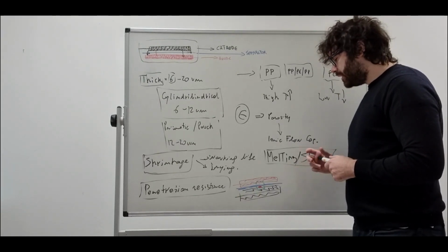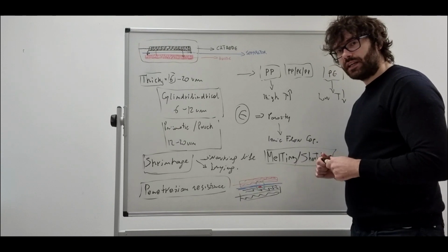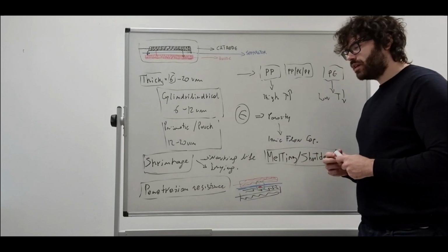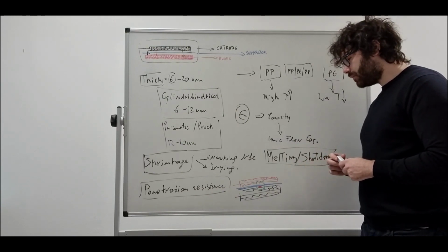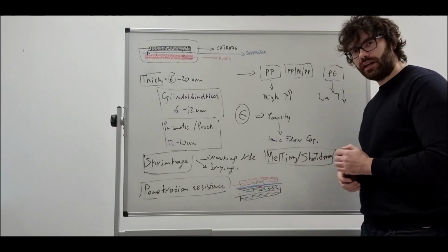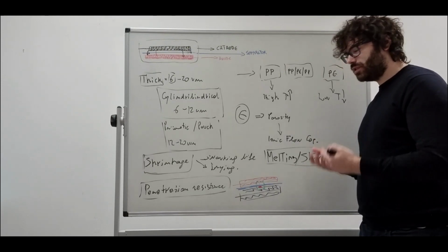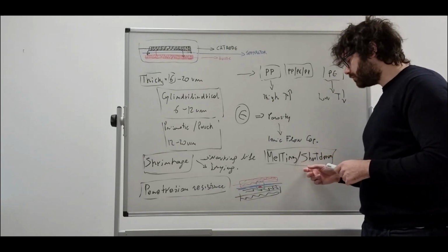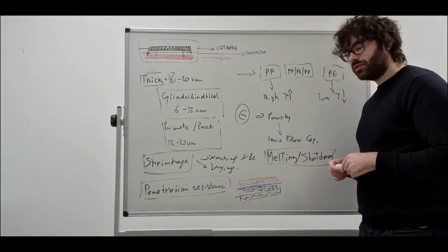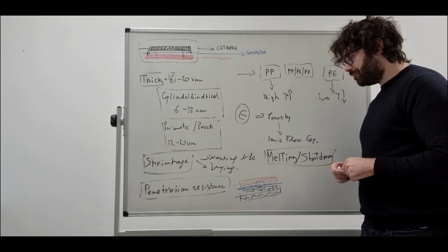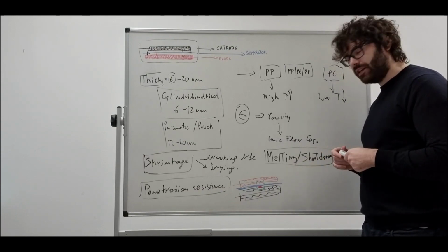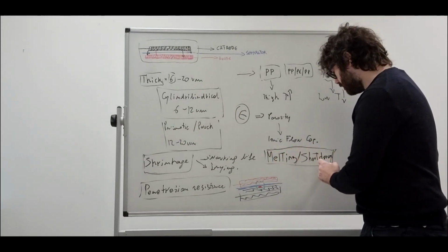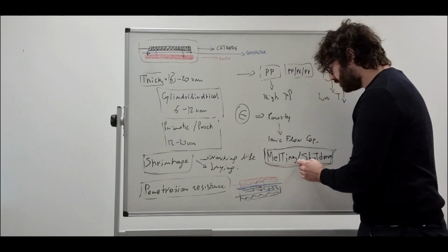occurs, the internal temperature starts to rise very quickly. Okay, since the failure triggers some chemical reaction, exothermic chemical reaction, which produces heating. Okay, and the heating accelerates the kinetics of the chemical reactions themselves, and this is a chain effect. Okay, so there is a passive safety property of the separator